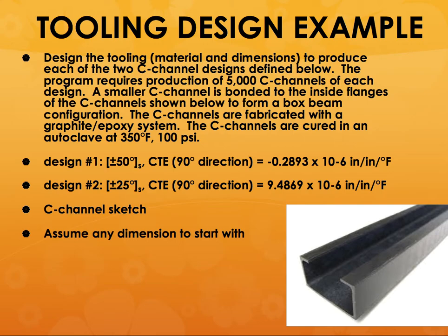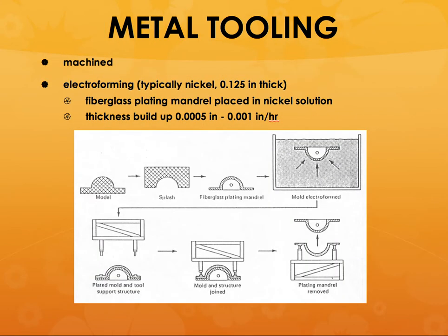But if you had design number two, where your fiber angles are plus minus 25 degrees symmetric, your CTE can be positive, and it can introduce a lot of complexity into your tooling design. So those are some of the issues that we have to really worry about.